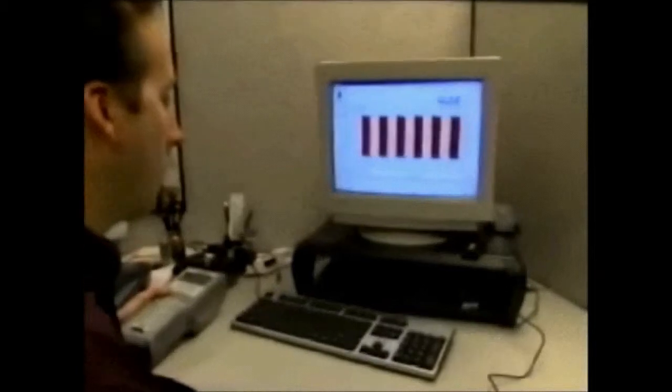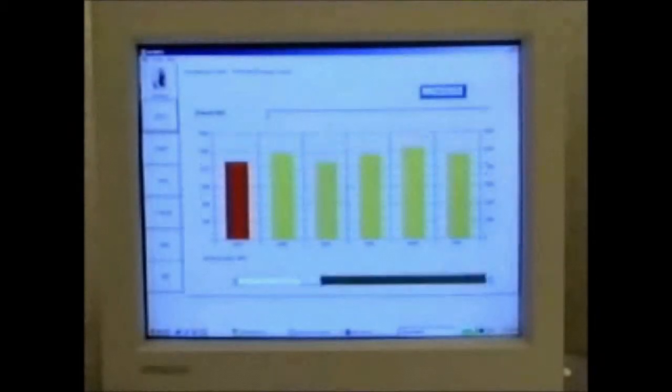For further information on testing with the Celtron analyzer, refer to your instruction manual and the quick reference guide. Determining whether a jar is good or needs to be replaced is not simple. Consult with the manufacturers where matters of warranties are concerned. Discuss your readings and observations with them before deciding a course of action. In general, we recommend following IEEE guidelines. Also consult guidelines set by the organization or company you're testing the battery for.